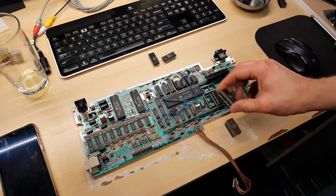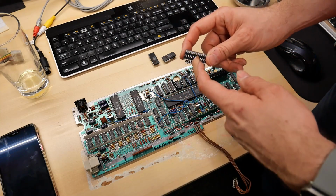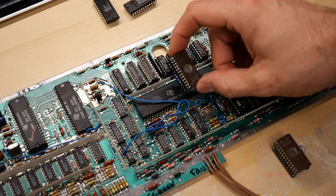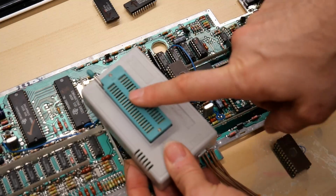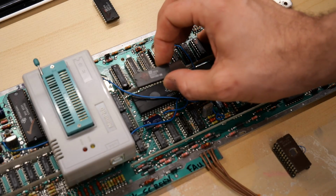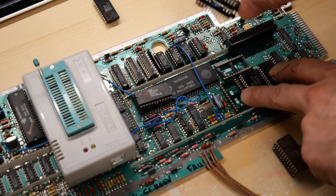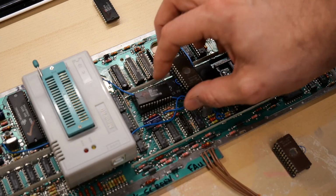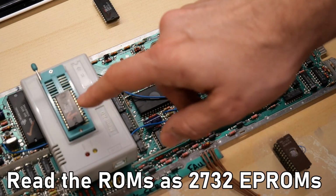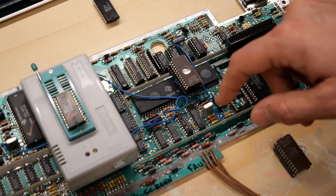So I had a thought about these ROMs. I built these adapters so I could use these EEPROMs in this motherboard. But there's something I could do actually. Remember, the adapter just swaps around 2 of the pins on the EEPROM, which makes it compatible with the motherboard pinout. These are 2732 EEPROMs, which are fully compatible with being read, not so much programmed, but read on my TL866 MiniPro. These original ROM chips are 2532s, which are not compatible with this. But what if I take these adapters that convert these sockets on the motherboard to be compatible with these 2732s and I plug them onto these EEPROMs? I should be able to read them inside the MiniPro, and that would actually allow me to read out the contents and compare it to known good ROM files, which I found on the internet, to see if these chips are good. All right, let's try this out.